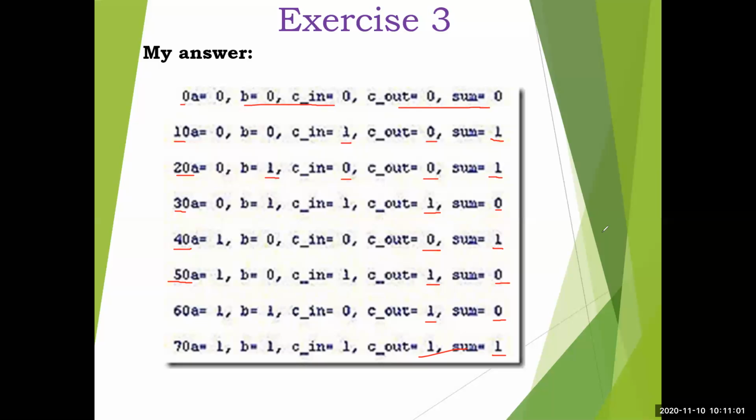That's what we have done. First we did the design, the gate level diagram. From that you wrote the Verilog description, and then you wrote the test bench, the simulation stimulus module, and finally we verified the output. Okay, I hope it is clear. So with this we have completed the 3 exercises. Another 2 exercises are there that we'll see in the next video.